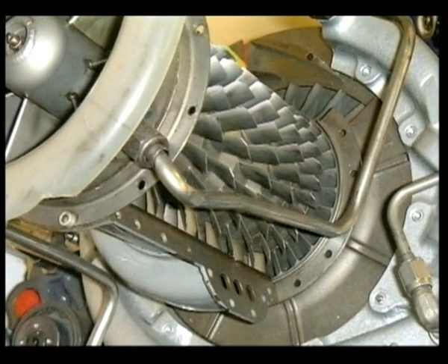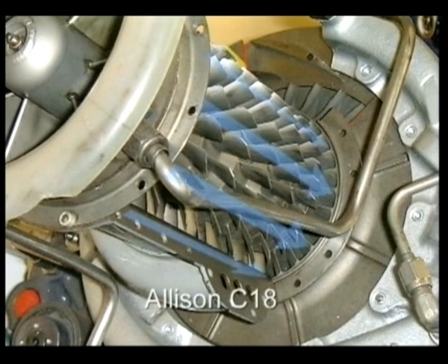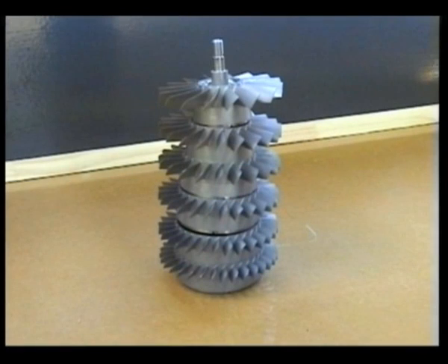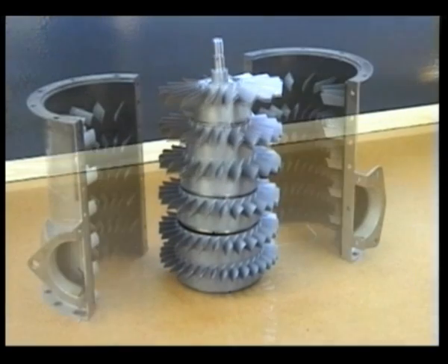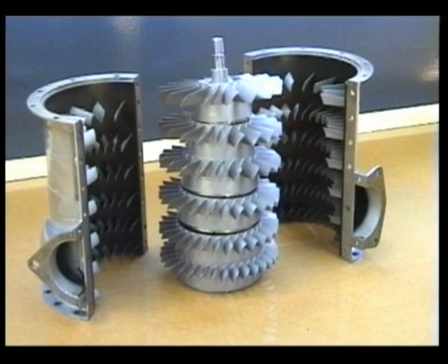In the axial flow compressors, the airflow is, as the name implies, axial, that is, parallel to the axis of the engine. At each compressor stage, the air is accelerated by the rotating blades prior to entering the following ring of diffusing or stator vanes. In so doing, the compressor converts kinetic energy into static pressure energy.